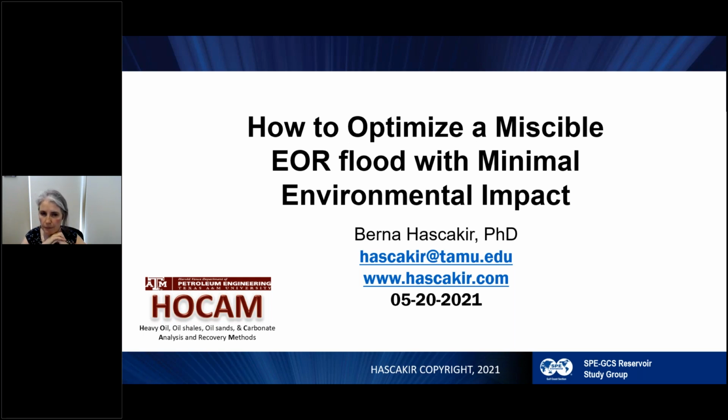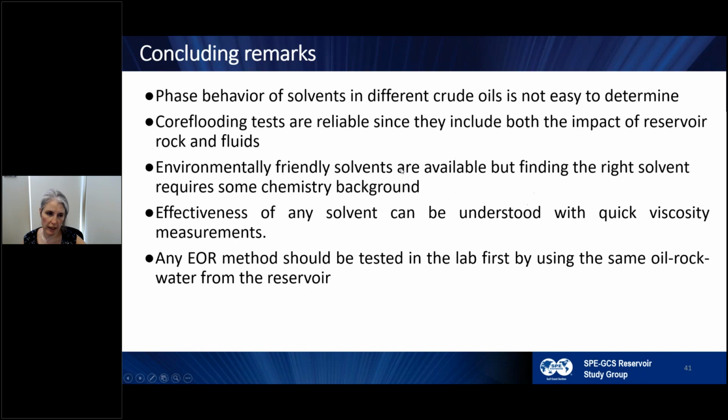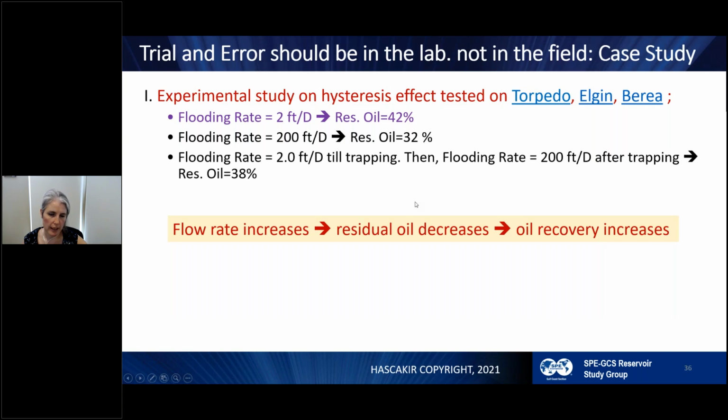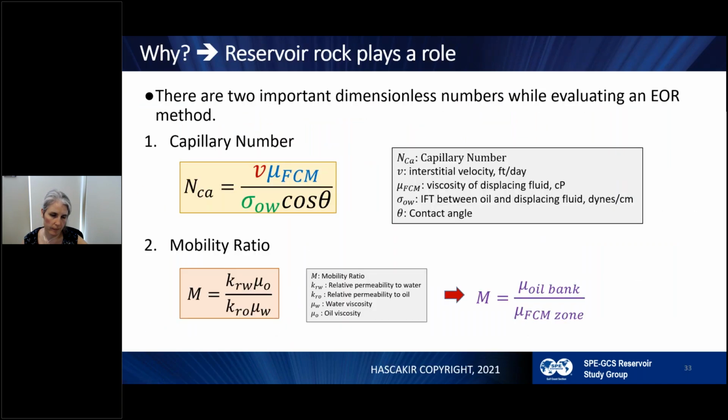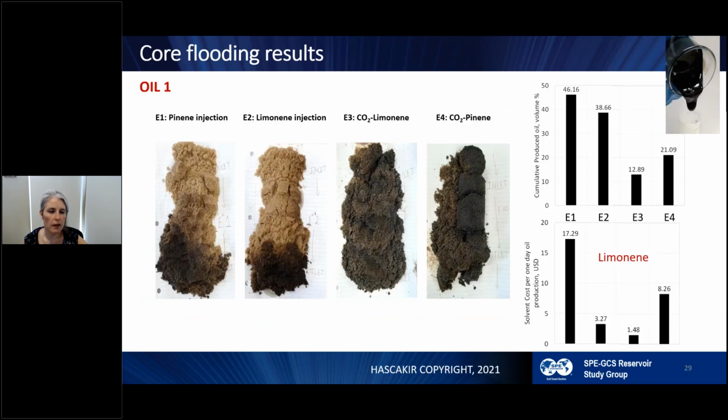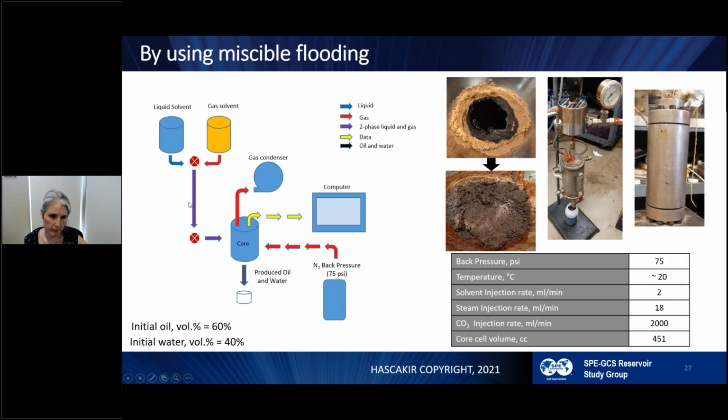This is a good question, really. So in terms of produced oil, what we have seen, because we have also, here, I didn't show those results to you, but here I have 60% oil and 40% initial water. Because of this initial water, we have realized in some produced oils emulsion formation.